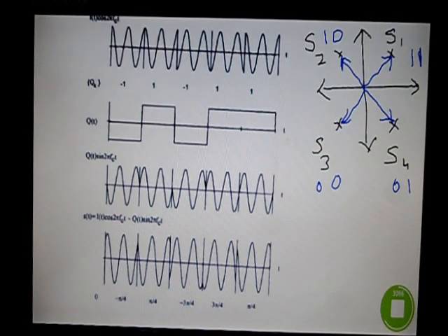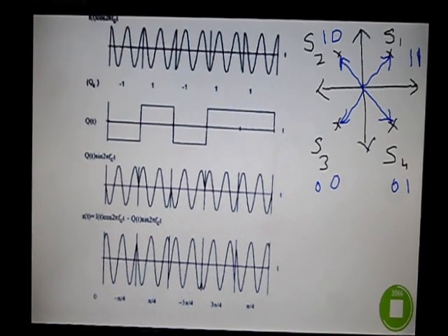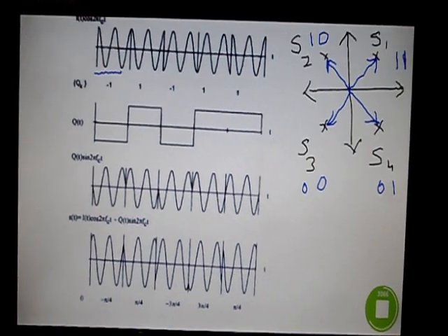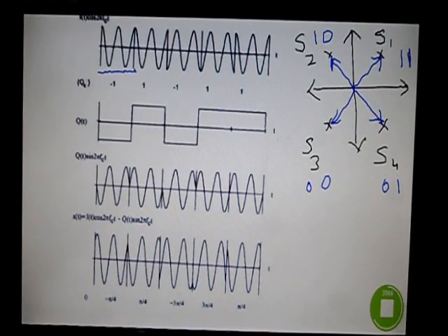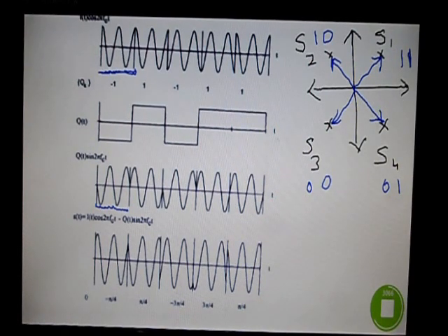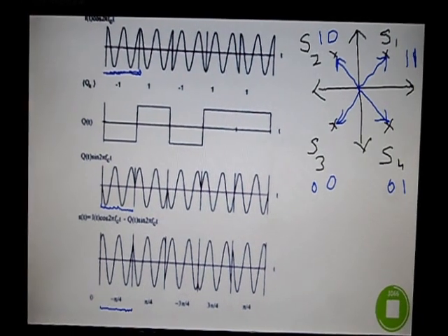If you observe the first 2 bits in this diagram, you have the first waveform from the I channel and from the Q channel, the modulated sinusoid carrier. When we add this, we get this signal, and this signal has a minus pi by 4 angle.